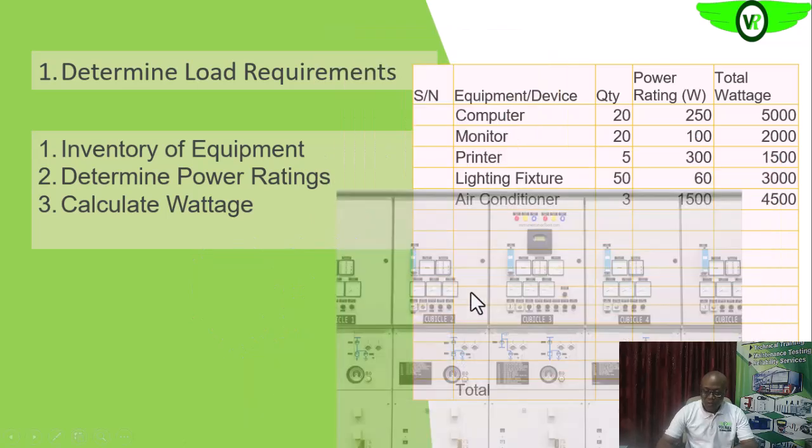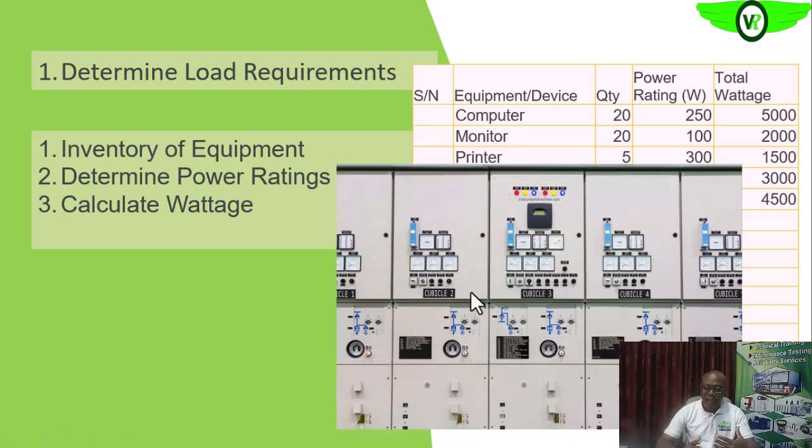So if you have maybe a switchgear in such a facility, you find the current reading on those, and if you are lucky, you also have power meters on the switchgear. Are we getting it? Once you have those power meters, you just get the wattage reading directly. If not, take the current reading and multiply it with the voltage reading.